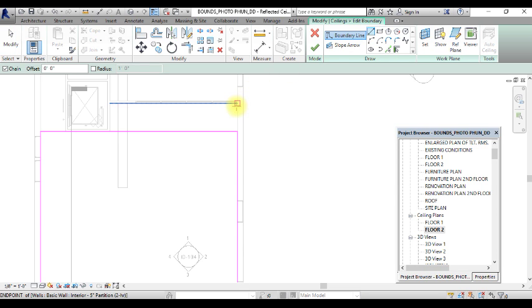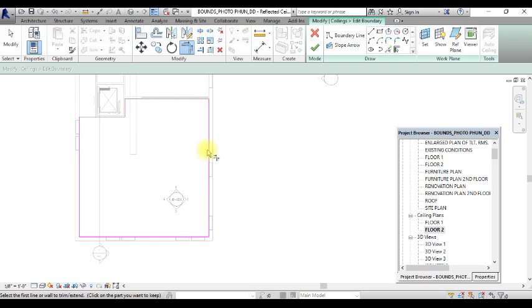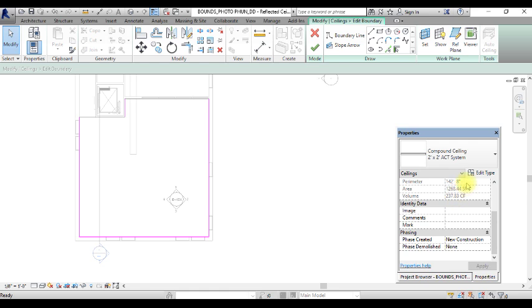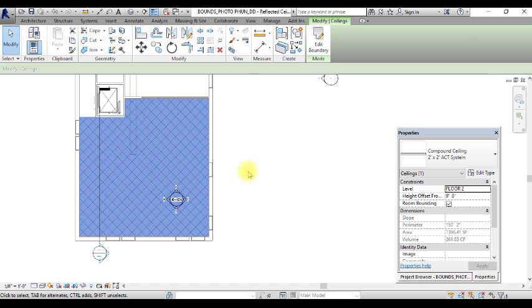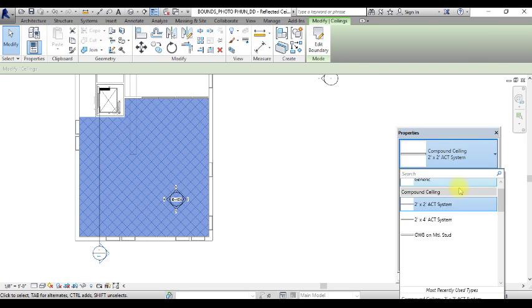And as you can see on the second floor, when we draw this ceiling, it's actually going to need to extend into this little niche area, and I'm using fillet just to clean that up. And I have a ceiling in there, and here's how we set the level. We're going to go over to the properties tab, and from the second floor it is 9 feet off of that floor. Of course, it's more like 18 feet off of the other floor.